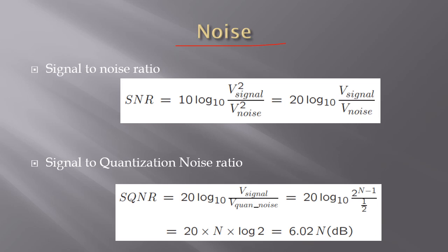Now, the other noise comes from the quantization. Remember that part of the sampling was quantization, the second step. At the sampling itself, we have a signal in a fraction, so basically there is no noise there. But when we quantize into the nearest integer, then we introduce a noise, which is half of the interval of the quantization.